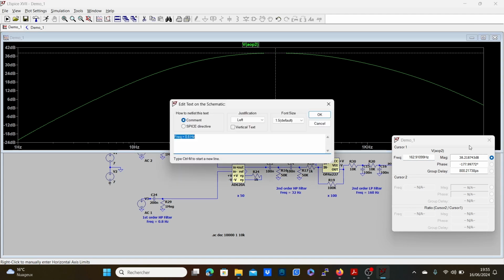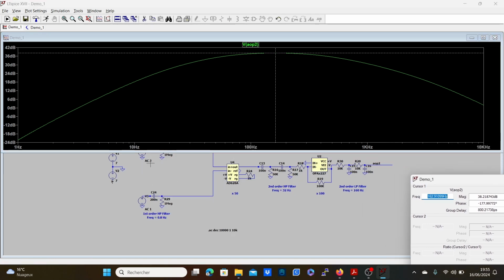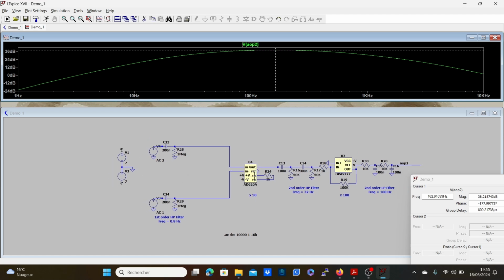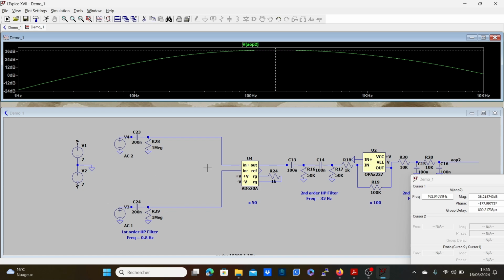something that I forgot to mention. As you can see here, it's a differential op-amp. I'm just assuming, it's just something that I took conventionally, I made sure that I had a difference, like 2 minus 1 will give me a unity gain here. It does not necessarily mean that when you're contracting your muscle the strongest potential will become this, because when you're not contracting your muscle, normally you're at the same potential, so you have 0 volts. And when you're contracting your muscles, you're going to create a difference in potential. And I don't really know what's going to be the value of that.